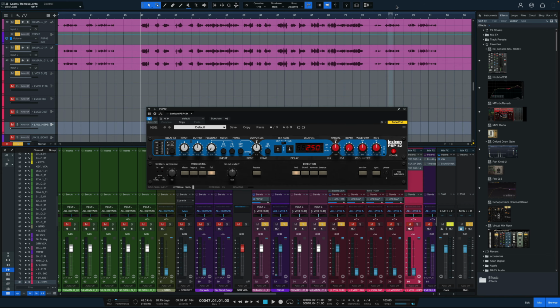Version 2 adds some more precise modeling of the hardware's audio path and allows you to choose how much of the character of this original hardware unit you would like to use. It also adds up to 28,800 milliseconds of delay time, has an adjustable high-cut filter frequency, LFO tempo sync and waveform phase adjustment, adjustable input sensitivity to simulate -10 dBV or +4 dBu operation, modeling of the original hardware's analog limiters and the AD and DA converters, plus a whole bunch more. So a really big update to this plugin.